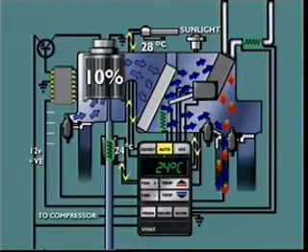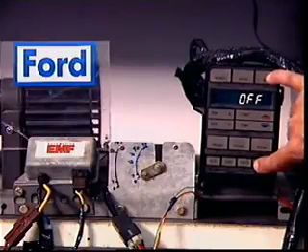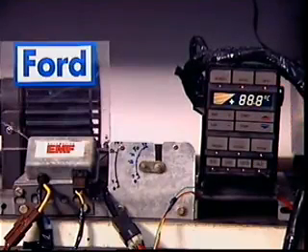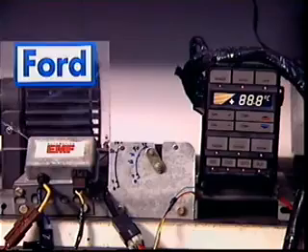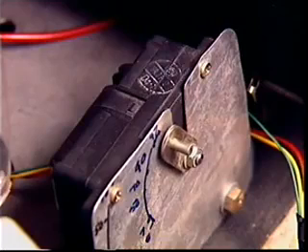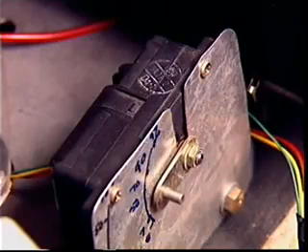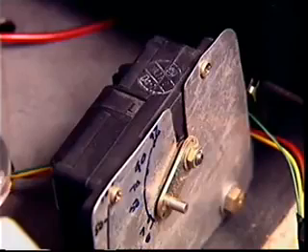Movement of flaps and valves can also be achieved by using electrical motors that respond to output signals from the electronic control unit. An electrical servo motor is used to move the blend door. It incorporates limit switches to open circuit the motor when the maximum travel of the door has been reached. This stops the motor from burning out.